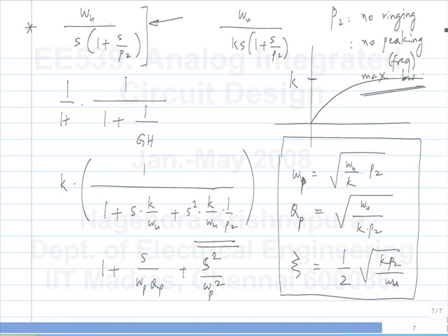So, the summary is that an additional pole causes a delay in the ramp response. And you end up with a second order transfer function for the closed loop. And because of the second order transfer function, the parameters are dependent on the second pole. So you can get either critically damped or underdamped or overdamped response. Okay, so you just figure out the constants.